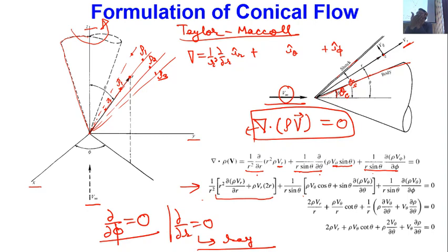Like in case of wedge, in case of wedge we introduce the planar symmetry condition. We consider that wedge width is actually infinite. So if wedge width is infinite, then at every plane along the width of the wedge, my flow structure will be identical. So considering that, we don't solve the variation of the flow in z direction, because it is not varying. At every plane we are saying that flow is same. So we consider that as a two-dimensional flow situation in Cartesian coordinate system. So similarly, for a conical case, we are having quasi two-dimensional flow or axisymmetric flow situation in nothing but the spherical coordinate system.